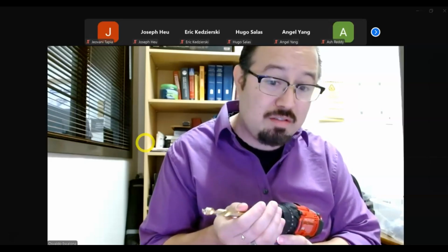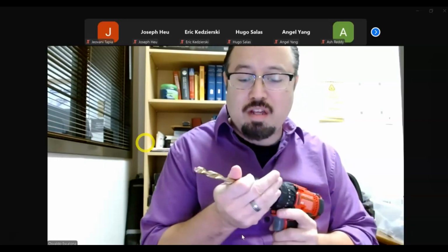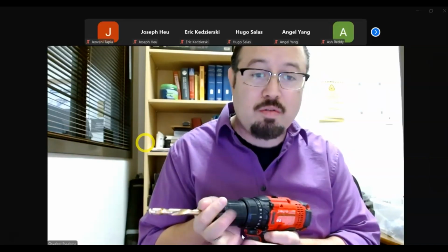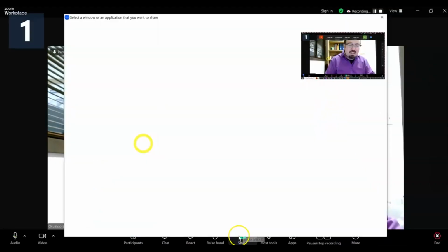If you put your fingers on the flutes, as this spins, it's going to cut you. So what you do is put your fingers on the shank. What's the shank? The shank is the part that doesn't have any flutes. Right now it's open. I'm going to hold it from the spindle and the shank slightly. I don't want to go too strong. Then I'm going to go forward, hold it, and let it spin. It's done. When I open it, I go backwards, hold the spindle, boom. Forwards, backwards. Okay, easy peasy.